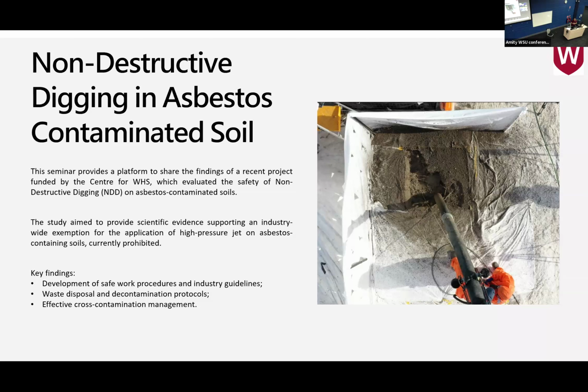If you've been to any construction site with excavation, you would know that in Sydney particularly, underground utilities are always a mess. Even when you have plans, when you borrow the plans from Sydney Water and different utility organizations, when you dig, underground is a completely different story. So non-destructive digging is an amazing solution for digging around underground utilities in confined spaces where you can't really access with a truck or an excavator, you have to crane them. You use this. So industry really wants to do it.